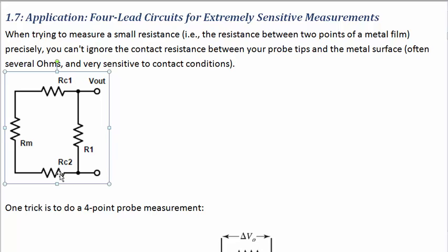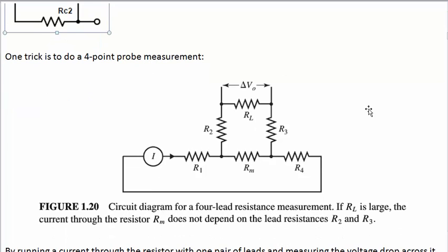You can try this yourself by trying to connect one probe to another one on a really sensitive resistance range, and see that it's quite tricky to do that with consistent results. So basically, this is not a good way to measure the resistance if it's a really small resistance compared to contact resistance. A better way to get around this is with what's called a 4-point probe measurement.